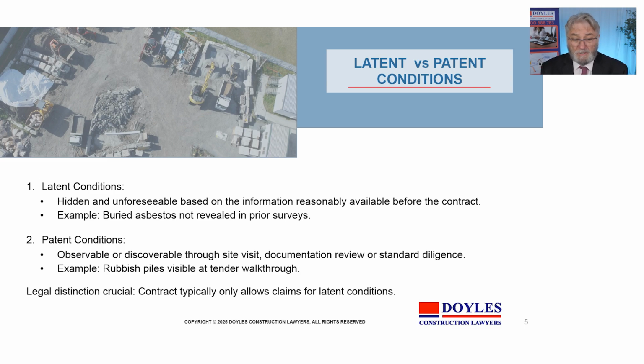The other aspect you've got to look at is patent conditions. Those patent conditions, usually, if they can be discoverable during a site visit, documentation review or standard diligence, then they're much more easily controlled. If there's rubbish piles visible at tender walk through, then they can be taken into account by the contractor and priced for removal. The legal distinction is crucial. Typically, the contract only allows for the conditions it contemplates and then has a provision which hopes to catch most of the latent conditions.